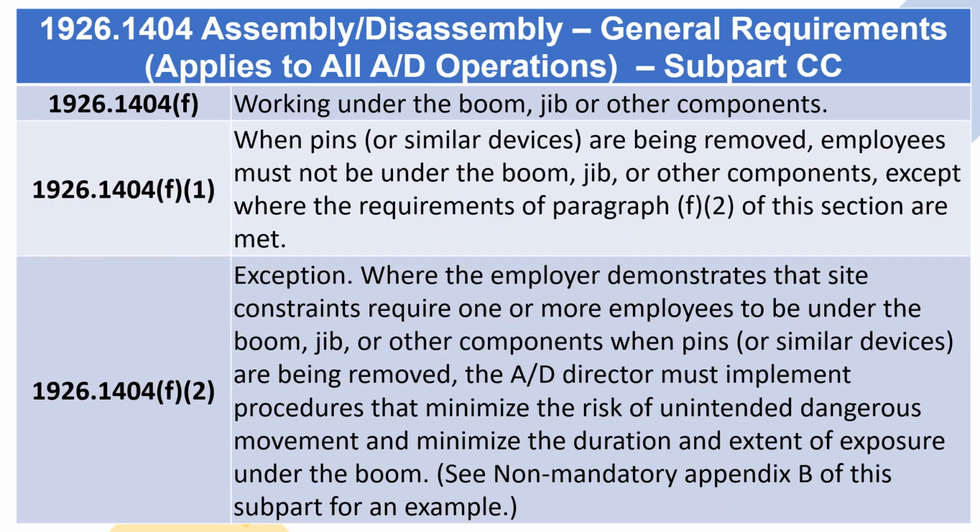1926.1404(f), Working under the boom, jib, or other components. 1926.1404(f)(1). When pins, or similar devices, are being removed, employees must not be under the boom, jib, or other components, except where the requirements of paragraph (f)(2) of this section are met.